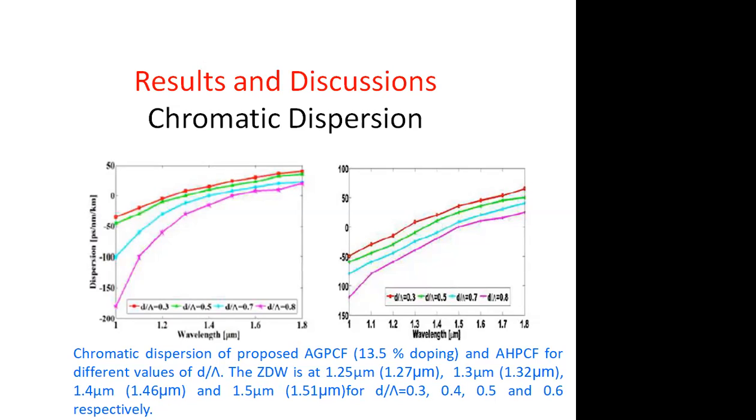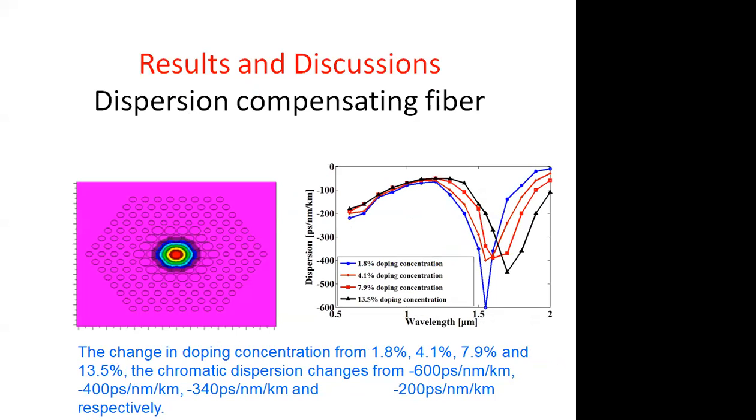And if there is dispersion, what will happen? All the pulses will collide with each other, and there is crosstalk. Right? So there is chromatic dispersion in single mode fiber also, and there must be a solution for this. Let us assume that over a length of 100 kilometer, the accumulated dispersion is, say, 100 picosecond. The unit of dispersion is picosecond per nanometer kilometer.